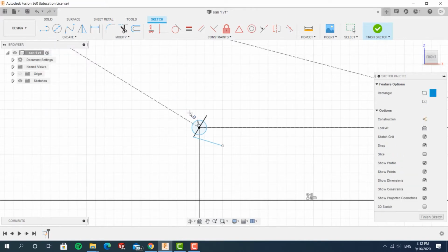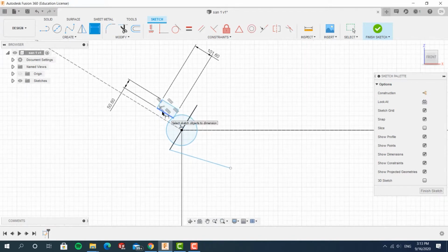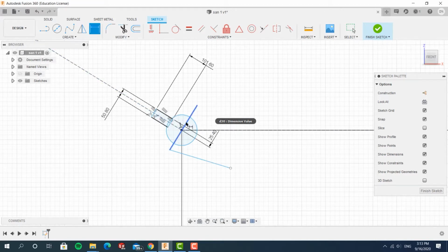This mechanism is, as I said before, going to be a simple two-wheel shooter, but you can actually change the angle of it by changing the distance between a point on the actual robot and a specific point on the shooter by unscrewing a long big screw, which will be connected to a very slow motor.